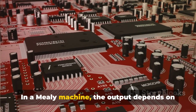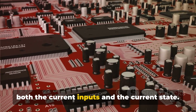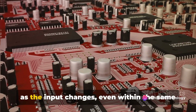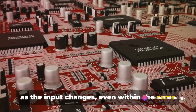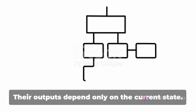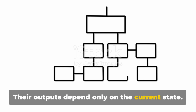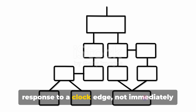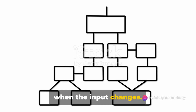In a Mealy machine, the output depends on both the current inputs and the current state. This means the output can change as soon as the input changes, even within the same clock cycle. On the other hand, Moore machines are a bit different. Their outputs depend only on the current state. This means the output can only change in response to a clock edge, not immediately when the input changes.